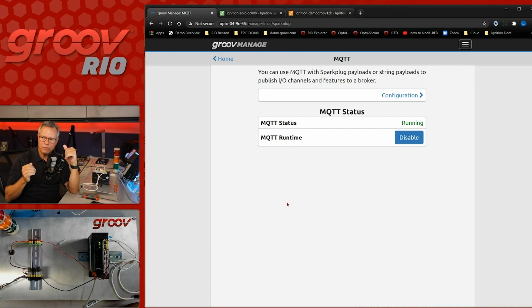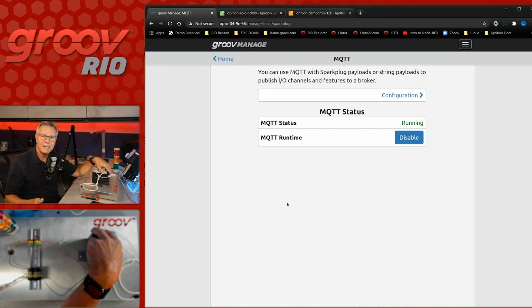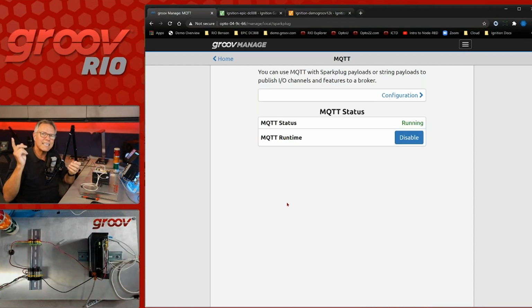So when you start thinking about how you put these systems together, if you go to your IT department and they say, whoa, we don't want any more devices on our network, you can say, these devices are DHCP'd. They're all outbound connections. We don't have any firewall ports open. The only port that's open on this device is 443, so I can get to the web server. For Doug, he did open up another port, 8502, so that it would respond to Modbus requests.